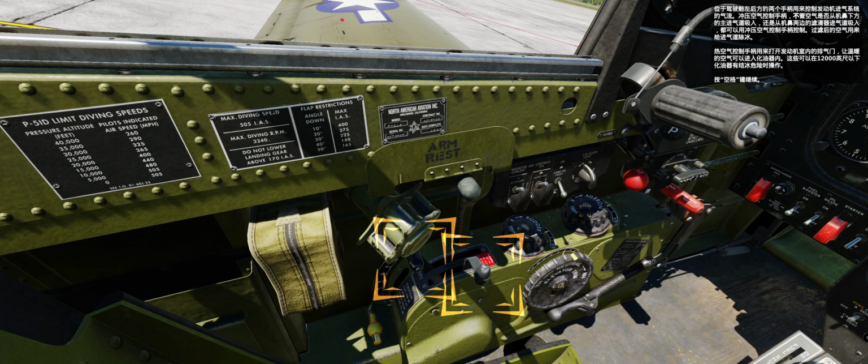The two handles toward the left rear of the cockpit control airflow to the engine induction system. The ram air control handle controls whether air is ingested through the main intake under the nose or filtered intakes on either side of the nose. Filtered air is used when icing of the intake develops. The hot air control handle opens a vent door in the engine compartment to allow warm air to enter the carburetor. This can be done below 12,000 feet when icing of the carburetor is a danger.